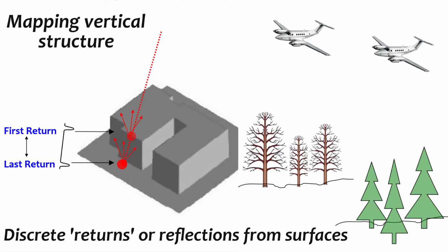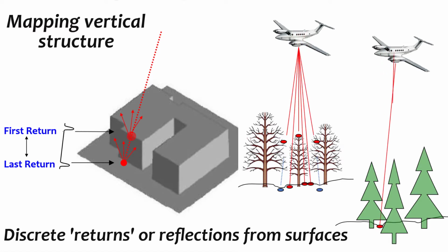The light energy returned to the sensor will be a function of the surface geometry, contact area, and its reflectance. Over structured targets like buildings or trees, the emitted laser pulse will produce an elongated waveform corresponding to the time over which the pulse interacts with those surfaces. In most commercial sensors, this response is broken down into discrete returns to produce a point cloud. In the case of vegetation, the foliage density, structure, and height strongly influence the point cloud geometry.